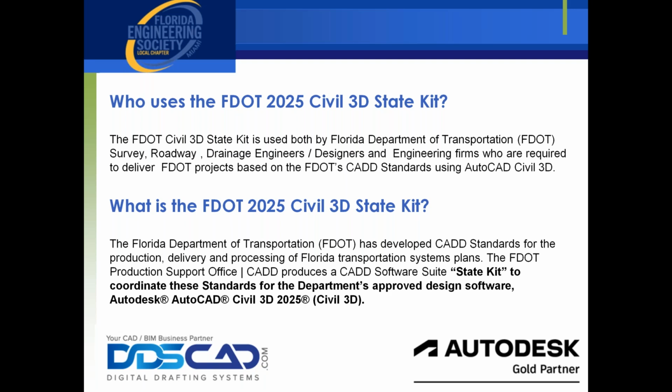It can't be done in a different application and then saved to a DWG AutoCAD format and delivered. It has to be done in a native Civil 3D format. So when those drawing files are opened up in the tool space, you're going to see surfaces and alignments and profiles and all the things that are associated with a true Civil 3D project.